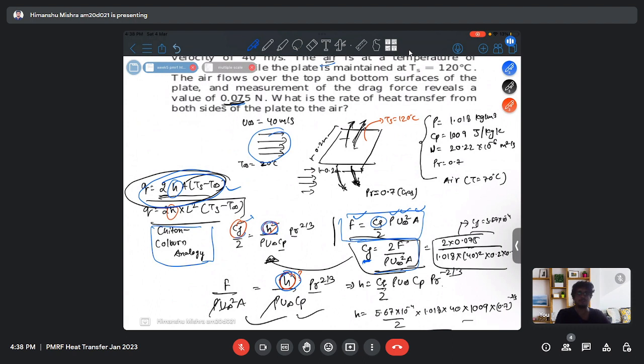No. When you are given any information about the drag coefficient or the drag force, then only should you apply this relation, because otherwise you are relating a new quantity, the drag force coefficient, to the heat transfer coefficient. The heat transfer coefficient is the unknown quantity in the question, and you would be introducing another additional unknown quantity.